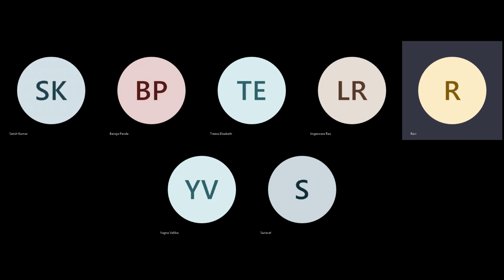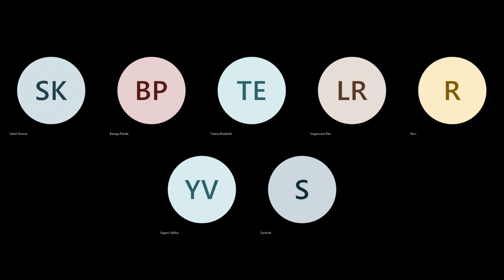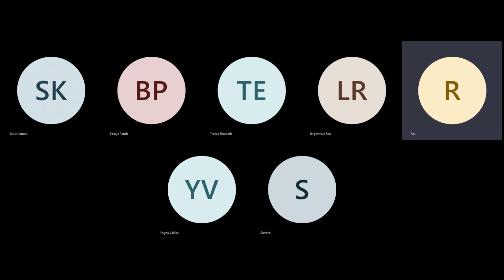So first, you have to understand your data flow diagram. You have to understand even before data architecture: what is this block supposed to do? Where are my IOs? How is this guy connecting? These should be answered even before you start anything, because only at the start will they answer these questions. Not when you are at the routing stage and you have a problem, they will say, what the heck were you doing? Why did you get lost, you could not close the timing? This is how it will happen. Only at the start do you have that window to ask these questions, so you should exhaust those questions then and there.